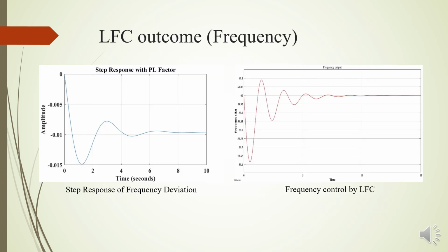Here is the output of the LFC in terms of frequency. We can see the first graph of the step response of the frequency deviation. The peak time is 1.223, rise time is 0.418 and settling time is 6.8. Also, the percent overshoot is 54.80. We can also show that in amplitude when the rise is coming over there. The signal has a high overshoot, and the response is very stable within 6.8 seconds, which is a very satisfying